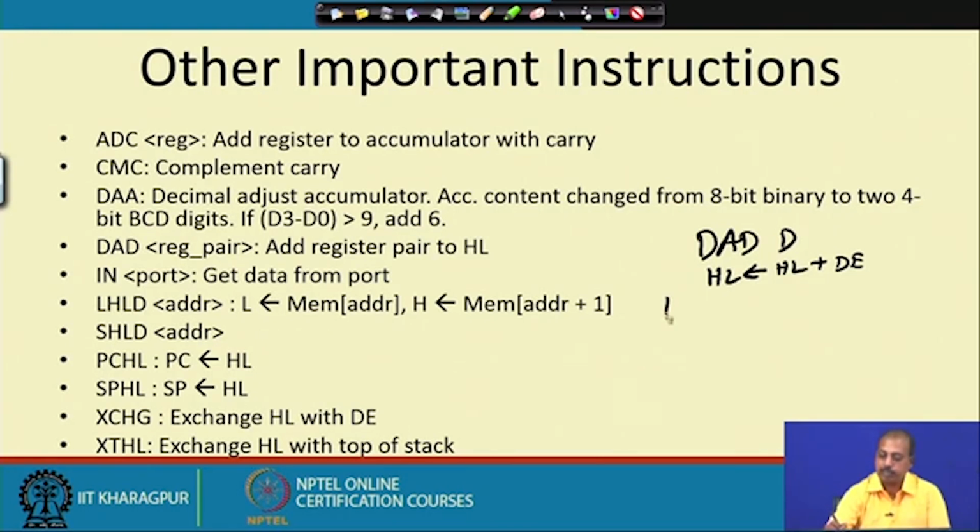Previously we have seen the LXI instruction, LXI H comma some immediate value. In that case the HL pair is loaded with that immediate value.